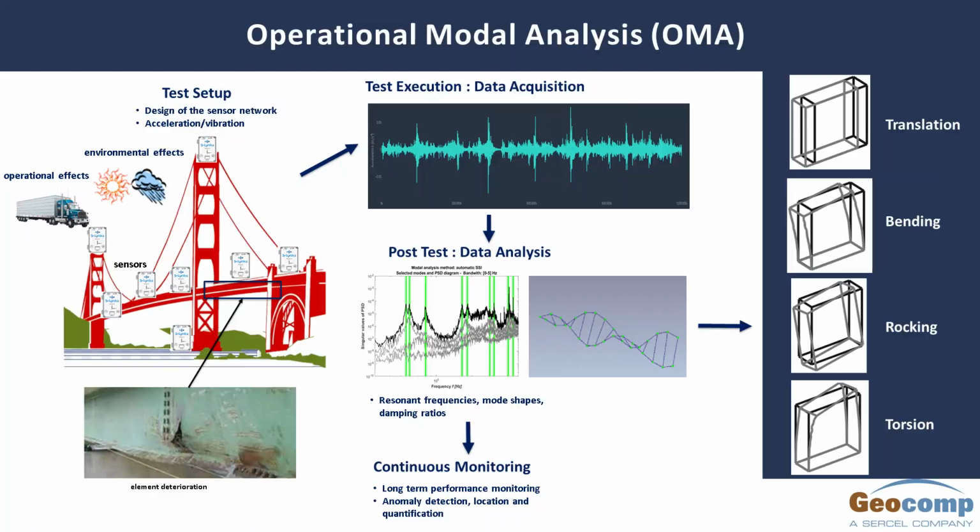So our system in this case is the bridge. Our inputs are traffic or weather conditions or any external thing. If there's a movable bridge, a bascule bridge that has machinery inside, all those things are input to our system. And then what we measure through our sensors is the output. So what you are looking at is an input-system-output linear time invariant system, and you are trying to resolve what the system looks like. This is a well-understood concept in electrical engineering and mechanical engineering, but it is a new concept for civil engineering. So what we are doing is basically understanding how the system is behaving.